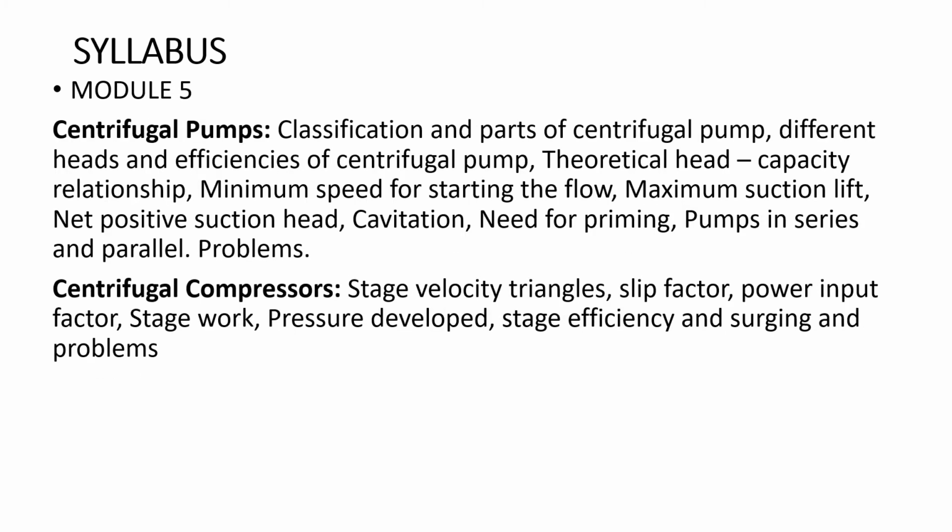Module number 5, the last module, is about centrifugal pumps and centrifugal compressors. Here too we'll be studying velocity triangles, the head, the relationship between capacity and head, minimum speed for starting the flow, maximum suction lift, and net positive suction head.